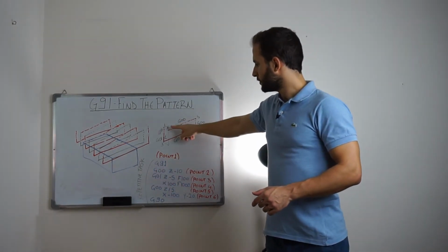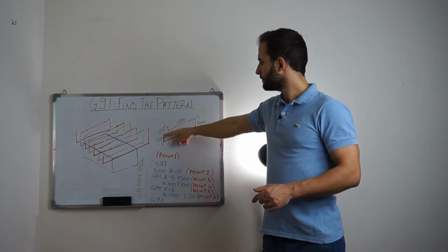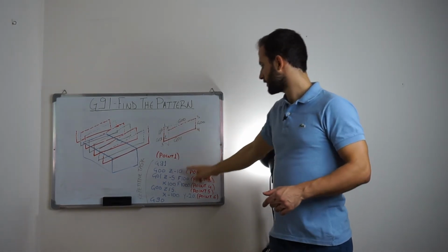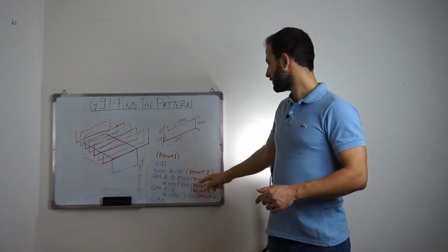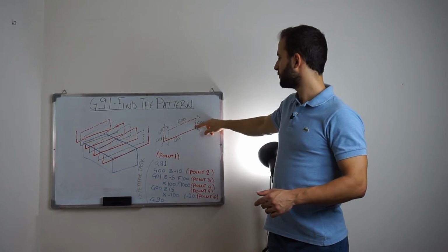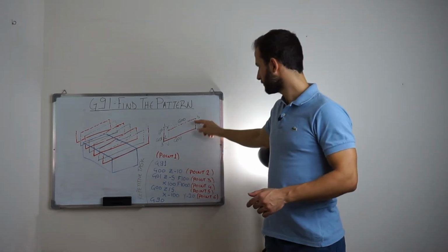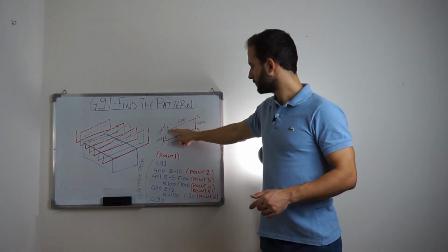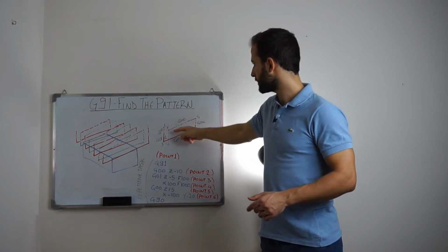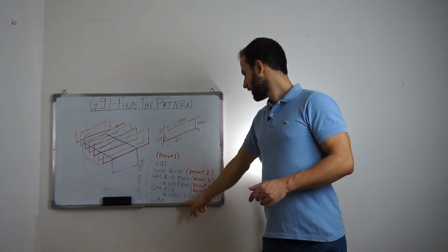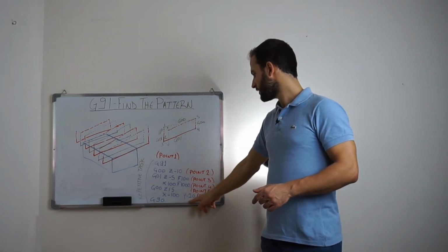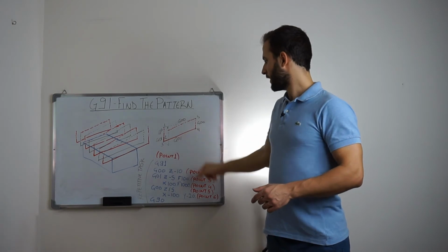and then we go down for 10 millimeters, then for 5 millimeters, then we go along the x-axis for 100 millimeters, we go up following a rapid movement for 15 millimeters, and then we go back to our new point 1, which is point 6, and we go back for 100 millimeters along the x-axis and 20 millimeters along the y-axis.